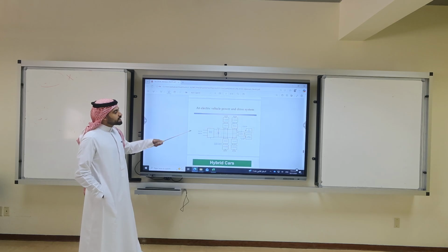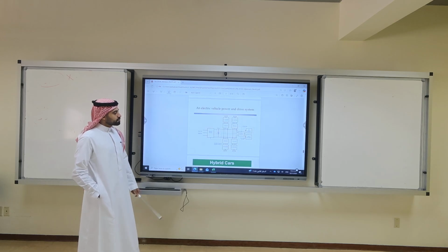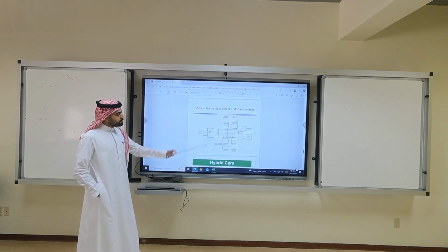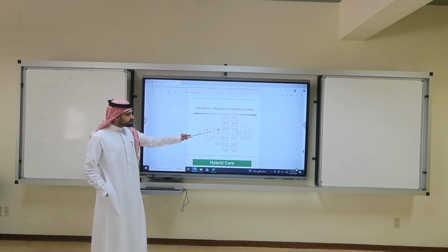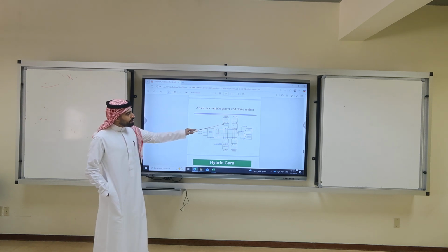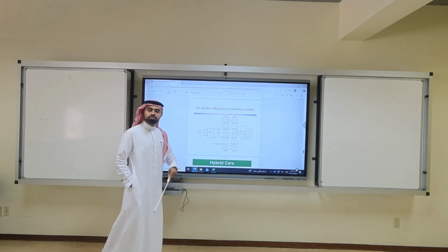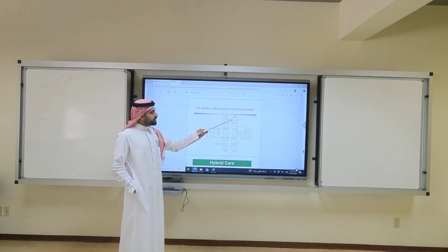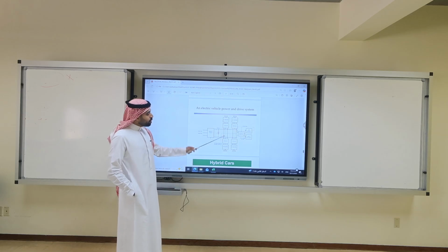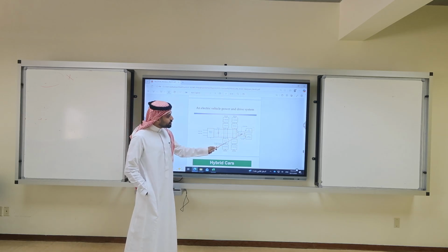The other application is the electric vehicle. We have a 3-phase supply, we have a battery charger, we charge the battery of the vehicle. Then we have 1, 2, 3, 4 inverter to convert to AC to drive an AC machine, an induction motor. Also, I have a DC to DC converter for low voltage DC for a microprocessor with controller, also for vehicle electronics.